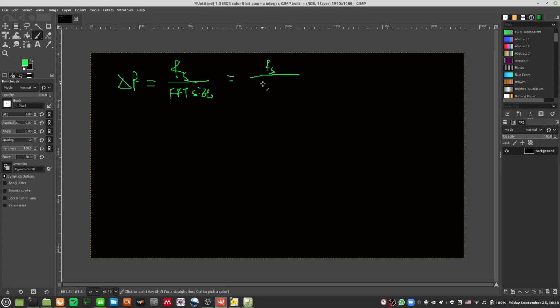What is the number of samples here? The number of samples is your time of your audio file times how many times you sample the audio file per second. So this is the time elapsed for your audio file, and this is how many times you sample per second. You multiply these together and you get the total number of samples, which is the whole FFT size of the array, if you take your whole array to be your FFT size. Looking at the formula, you have Fs on top and Fs at the bottom, both of which are sampling frequencies. So delta t is all that remains at the bottom, which is very convenient.